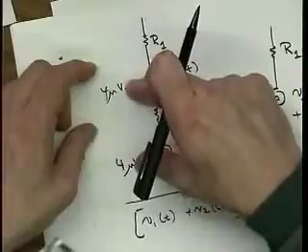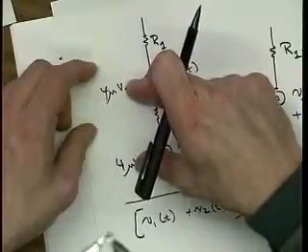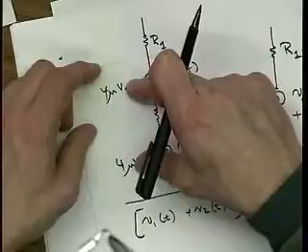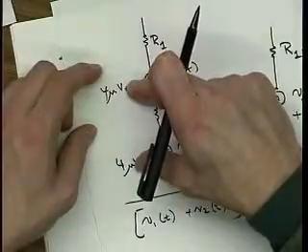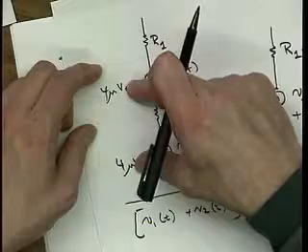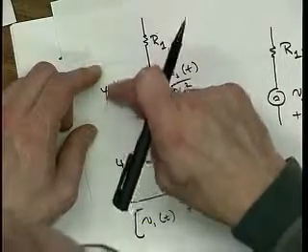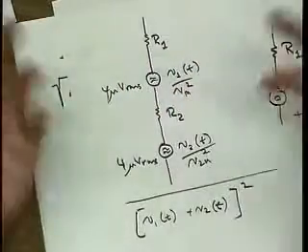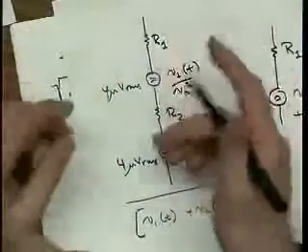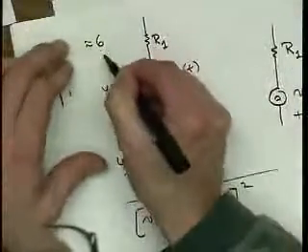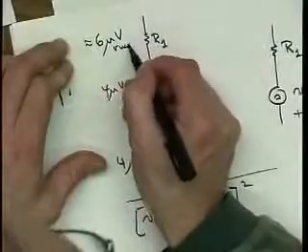It's the powers that add. So we have to square those, add them together, take the square root, and then we have the total noise of the thing. So this is actually 16 plus 16 is 32, and the square root of 32 is the square root of 2 times 16, so this would be about 6 nanovolts RMS total, right?